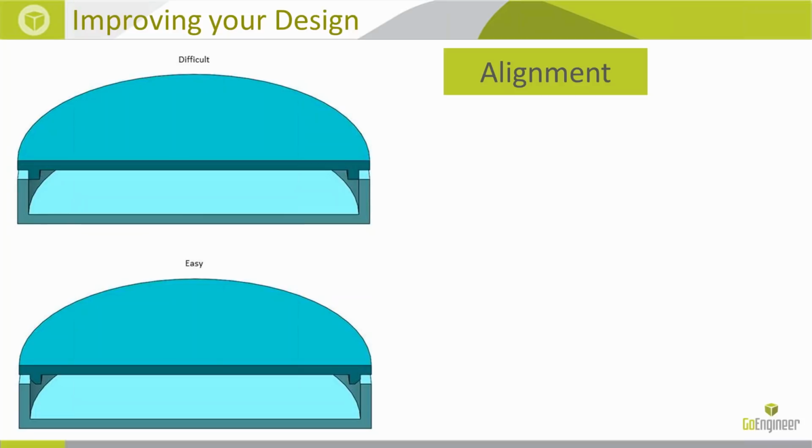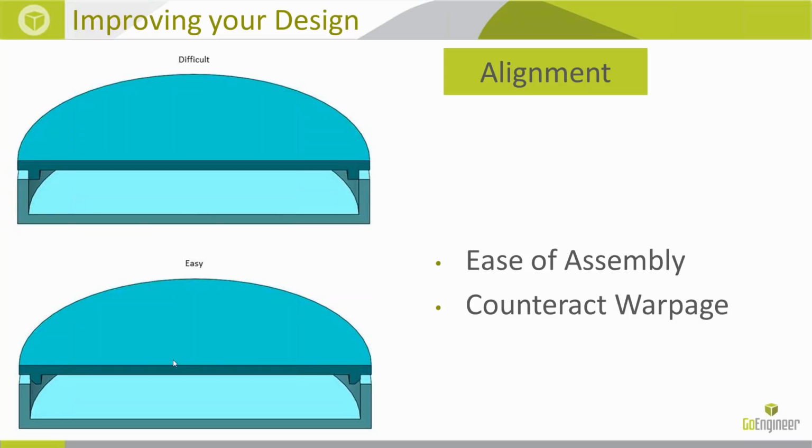Yeah, so that second diagram that you see in the bottom, you see the chamfer cut, and it gives you more room to sit in place. The additional room is because you want to account for warpage as one of the potential imperfections due to injection molding. So let's go in and look at what warpage is real quick.